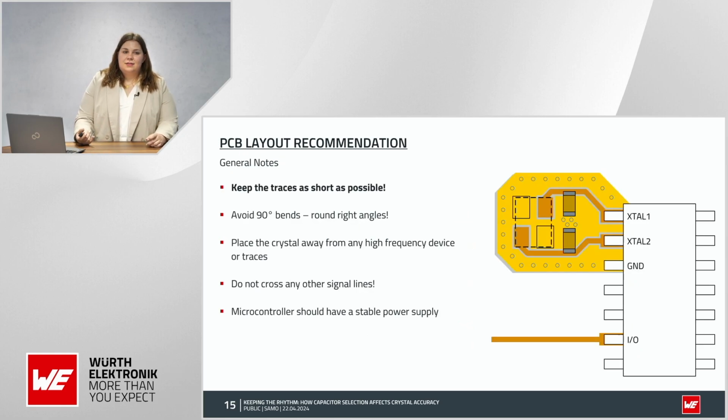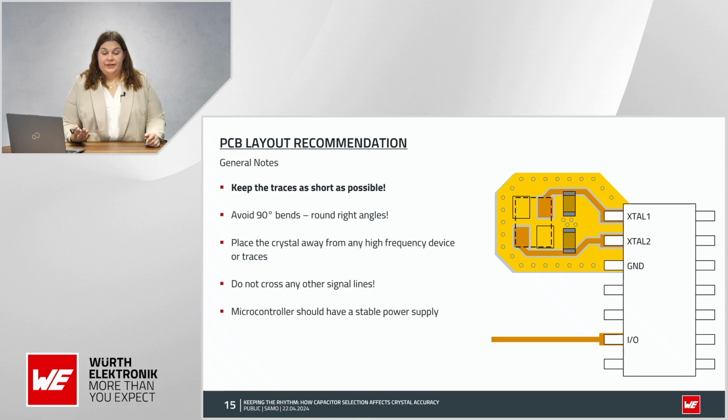So what other recommendations can I give to you to make sure the crystal is working properly? The first one is keep your traces as short as possible. As we learned, stray capacitance depends a lot on the traces. So the shorter they are, the lower the stray capacitance is. Also avoid 90-degree bends. It's better to have round angles.